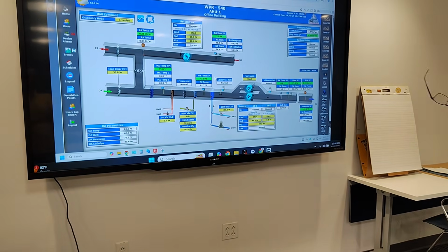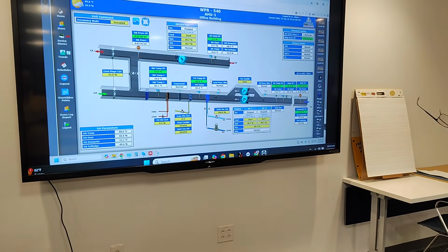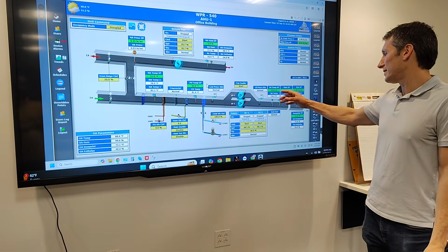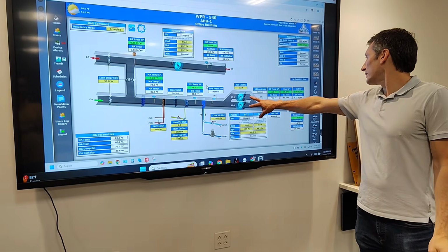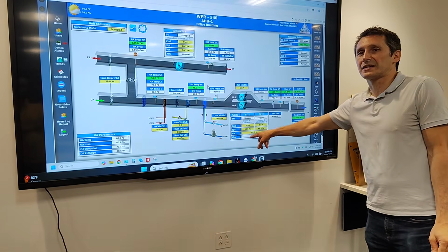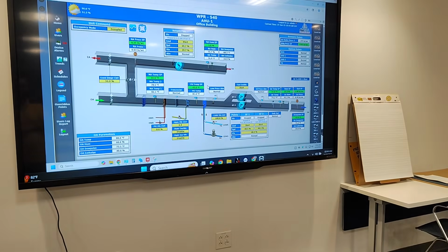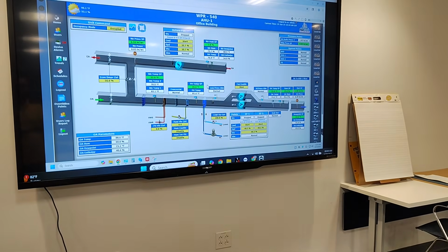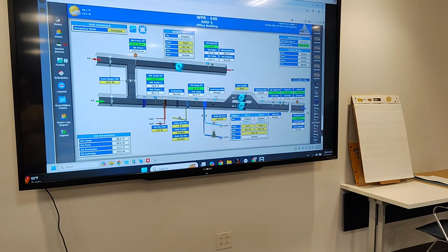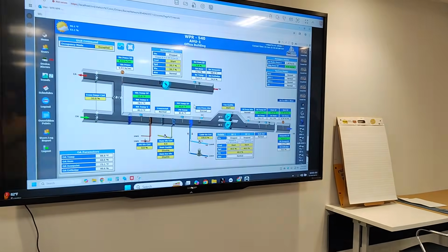At this point, I'm very curious to know what's happening up on the 7th floor. We cannot see. Right now, I really want to know what's happening with the fan. I believe the fan speed's at almost 35 hertz right now. So if we went up there, sure, it would say 35 hertz. Yes, because we did it this morning. We set it to 50 and went to 35 hertz. Right now it's at 48.6, so it'll be close to 35 hertz.